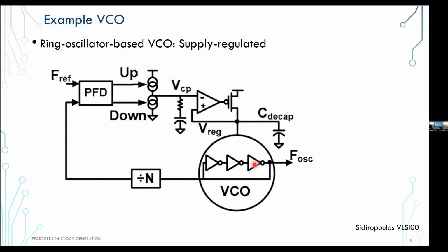However, the regulator will do some supply noise rejection, because up to the regulator bandwidth, it will essentially track whatever the reference is. So it's basically going to reject whatever comes from the supply. Of course, past the bandwidth, it's going to give up, so any higher frequency noise will enter.